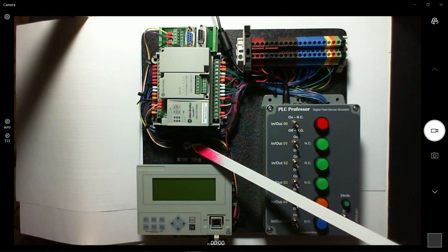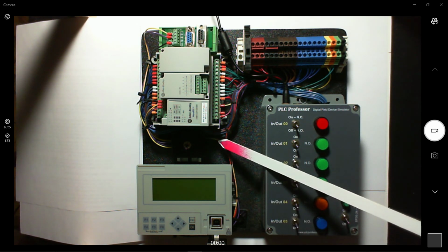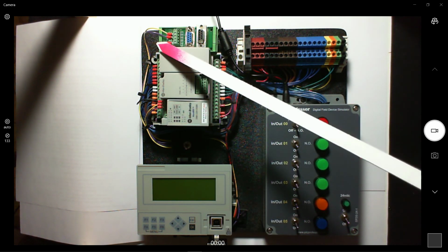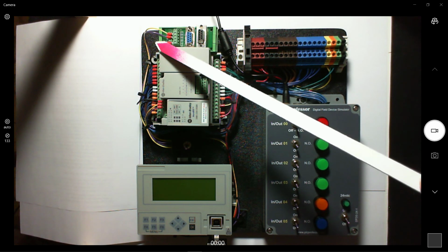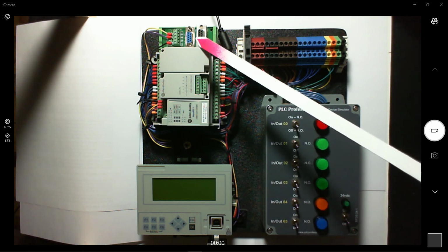They go to a double pole, double throw toggle switch. So the switch can pick between these yellow and purple wires coming from the remote LCD and these yellow and purple coming from the adapter. That way I can use the USB connector, or I can use the RS-232.